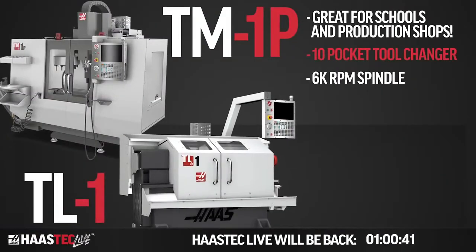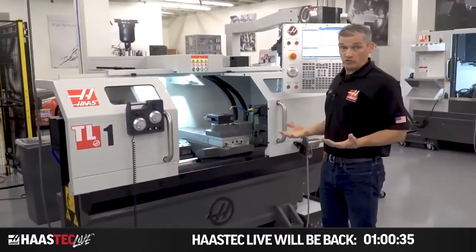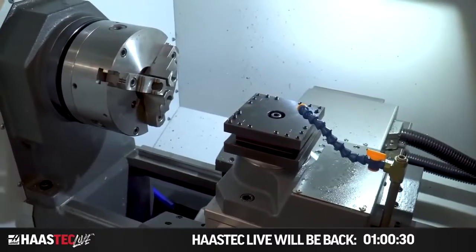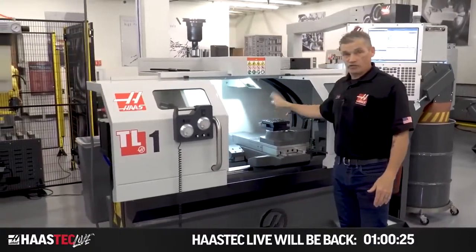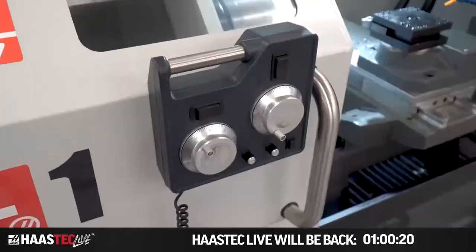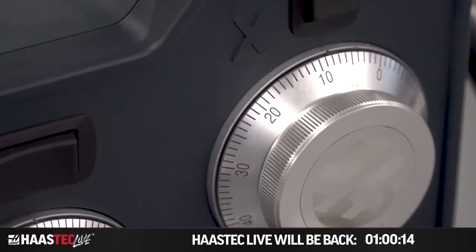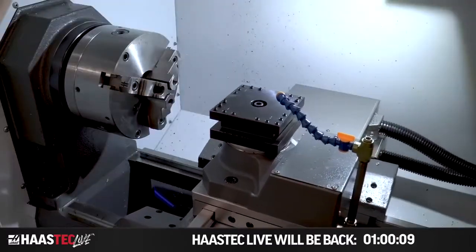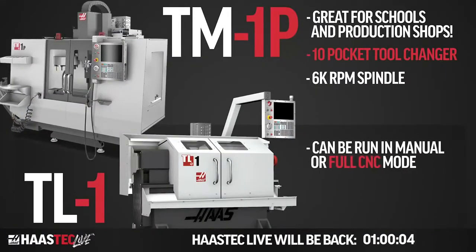All right, let's move over to the TL1. This is kind of the same concept here. If you're coming from a manually controlled lathe, then this layout's going to be very familiar. Chuck's right here, steady rest, cross slide. The basic version of this machine comes with a single tool post here. But in this case, we've got several options of this machine. We've got the E-hand wheels, is what we call them. This is kind of a manual method for jogging these axes around. You can see here, I can jog these very much how you would on a manual machine, but you can also run this in full CNC mode.